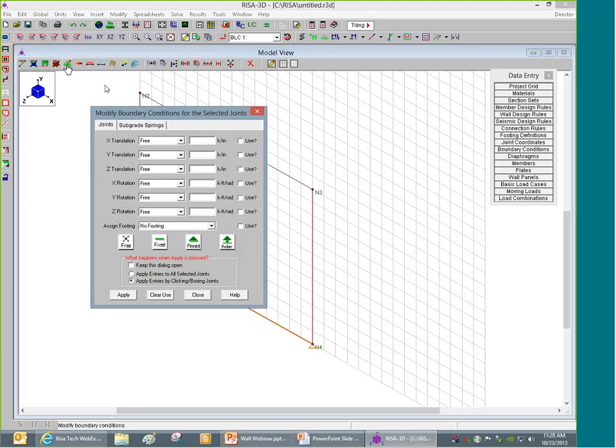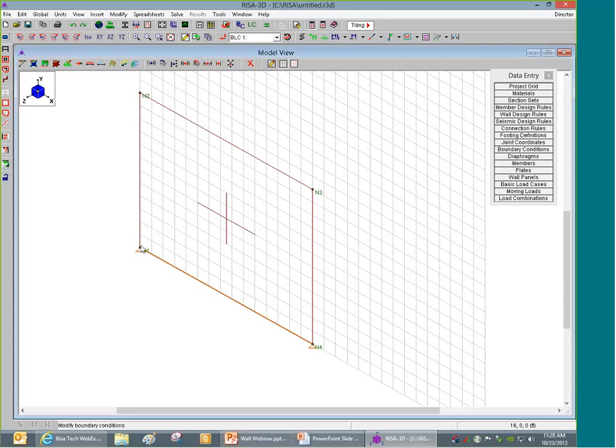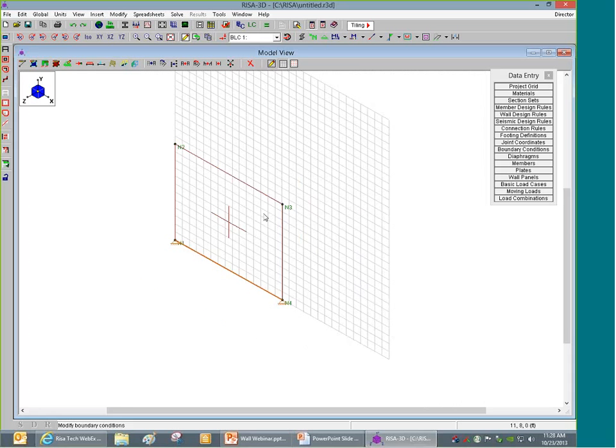That is the kind that I use for an individual node for columns and beams and the such, and just put one of those at each end of the wall and leave the rest of the wall free in between. That would cause this wall to sort of sag between those 2 points if I applied a vertical load. But in this case, we'll assume we have this continuous strip footing supporting it, so a continuous pin boundary condition is appropriate.